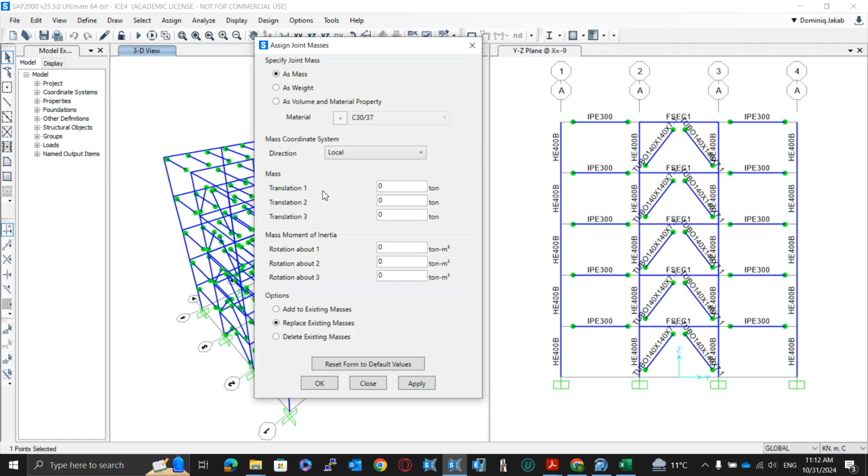You can neglect the vertical component even in seismic action in most structures, with exception of bridges or long elements, or if you have, let's say, towers that have spans, they have arms, with the cantilever arms, and that might have vertical effect. We are not in that case, so we should specify only that.